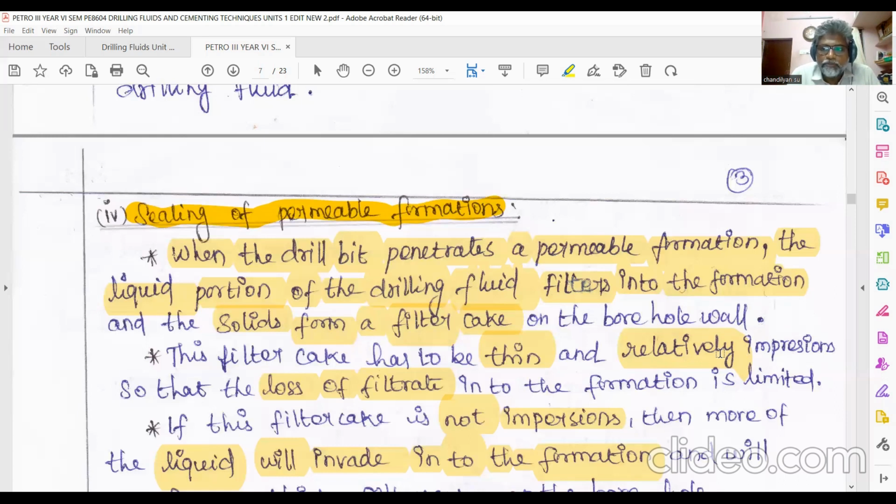If the filter cake is not permeating, then we don't lose money at all. We don't lose money in the sense of the lot of chemicals being added. We studied galena, barite, viscosifier, carboxymethyl cellulose, all these chemicals which would be lost in the long run in the micro channels, especially in the lost circulation zones and feed zones.